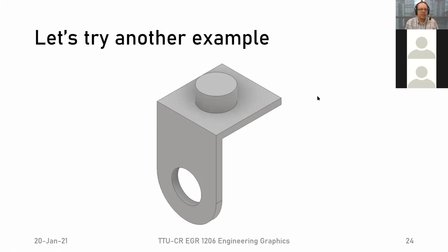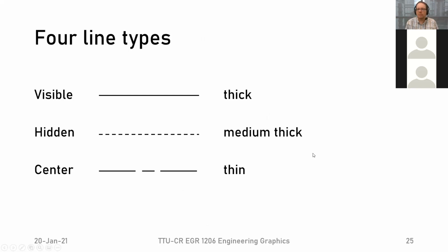Yes. Okay, good. Then, so this was how we treat circles. So now let's talk a little bit more about technique. We've talked until now about three different line types, right? We talked about the visible lines, and when we draw those they should be the thickest lines, right? Those were the ones that show us the outline of our entire system. Those should be the clearest ones. And then the hidden lines are dashed, of course, and they're not as thick. They're a little thinner than the visible lines, and then the center lines should be thinner than the hidden lines.